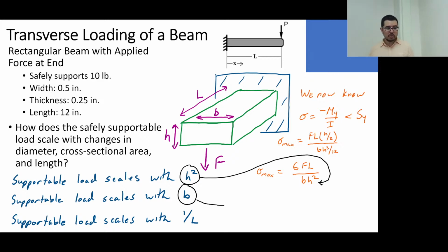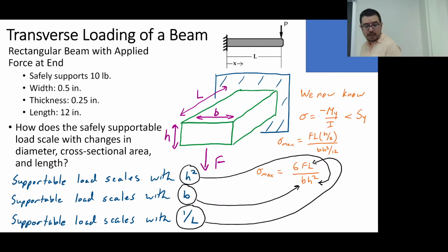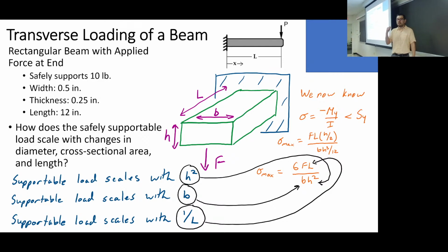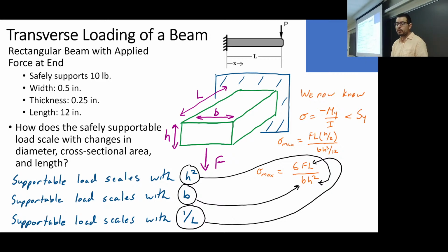You're like, well, you didn't include the transverse shear stress. That's true. Why? Because, as we discussed, or as you hopefully saw in the videos, bending stress dominates in beams as long as the beams are long. Remember we talked about double shear, and the idea that shear stress in a transversely loaded beam is not going to be large until it's really narrow. So we typically just think about bending, but you're going to be responsible, and we'll talk in the next little bit about what the transverse shear stress looks like, even though its magnitude may end up in practice being smaller. When we talk about combined loading, we're still responsible for knowing what the shear stress associated with a beam is.